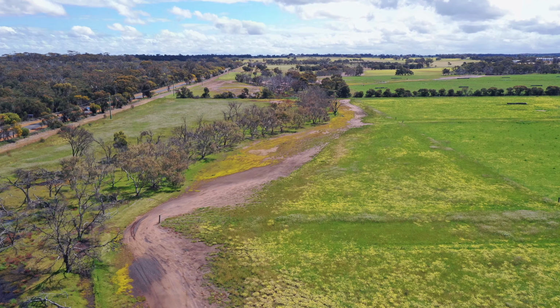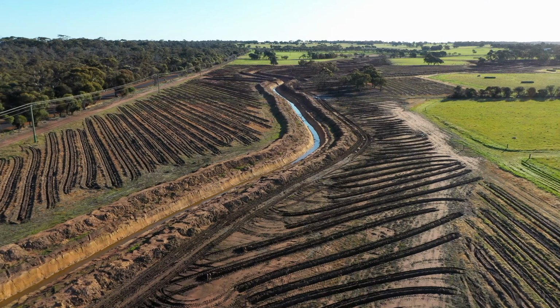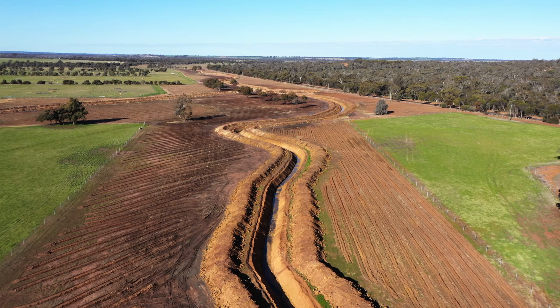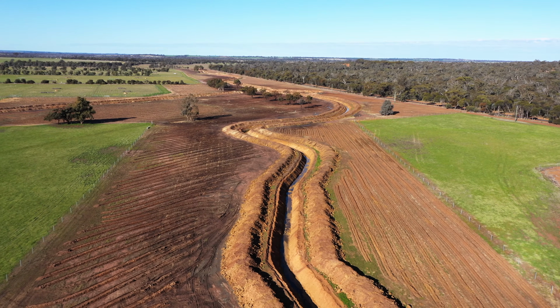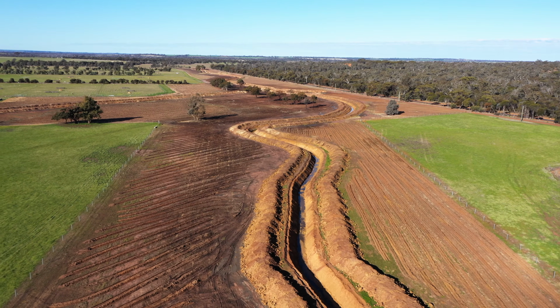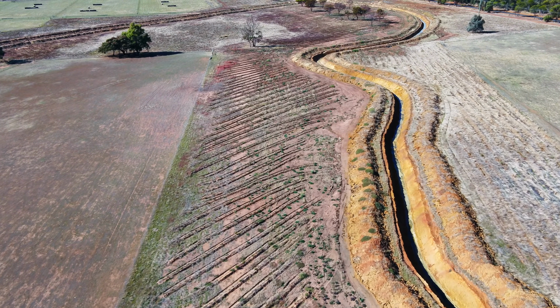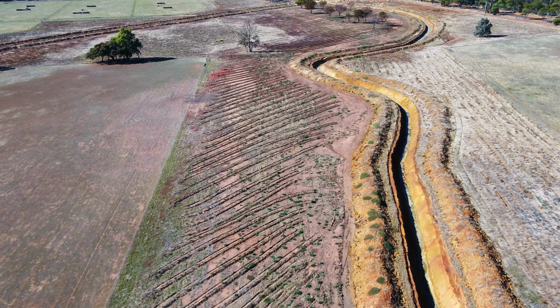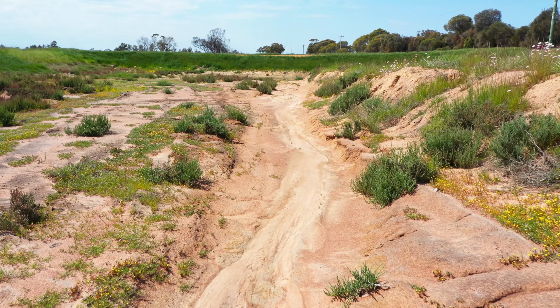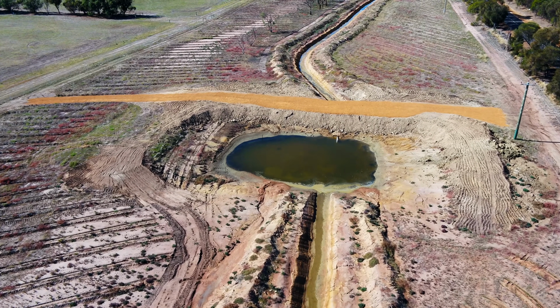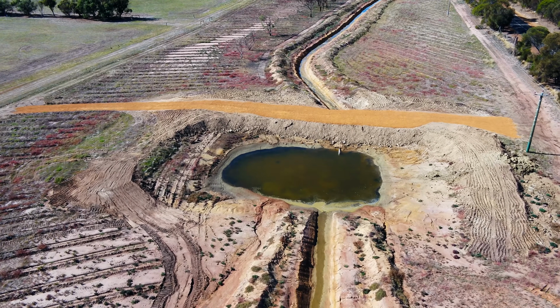And the other thing is we need to make certain we have full control of managing surface and groundwater flows. This is why we'll actually place the groundwater drain alongside a waterway, not in the waterway. And we use levee banks on both sides of the drain to exclude the surface water, which is very important. The surface water now is flowing down along the levees on the groundwater drain and managed in a very safe way, and we actually allow that water to discharge into the existing dams on the property to collect any sediments that may be flowing down the drain.